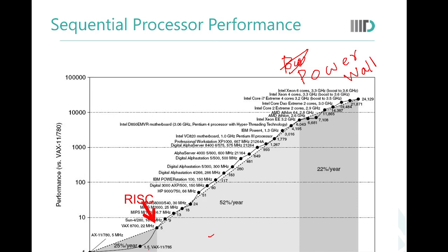There are a few things I think, for completeness, I should mention. The power consumed by a processor is directly proportional. Let me just write it down. I do not want to go into too much detail, but this is dynamic power. Dynamic power is power consumed because of switching. This dynamic power is directly proportional to the frequency at which the processor is running.